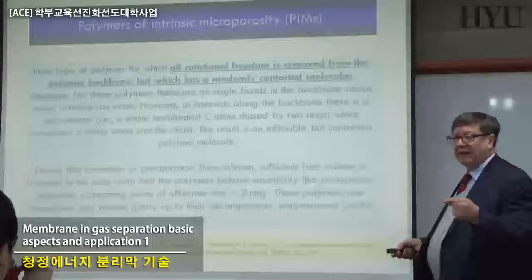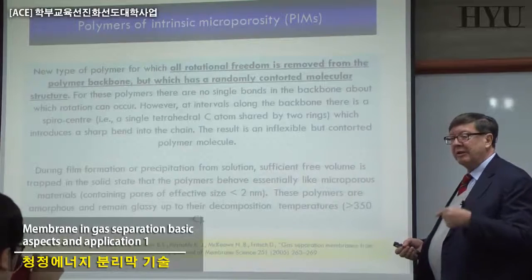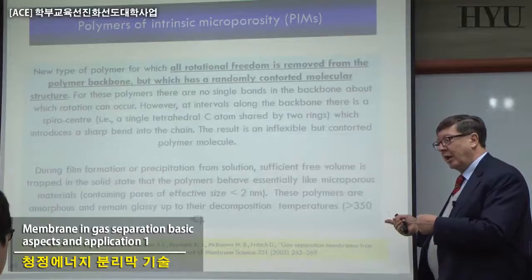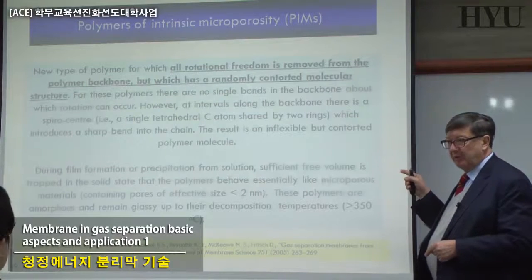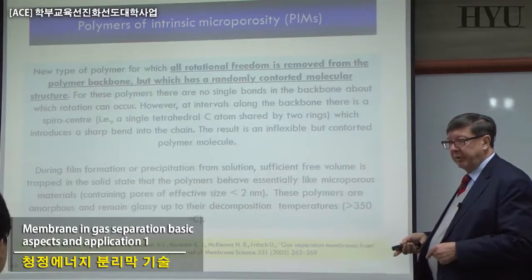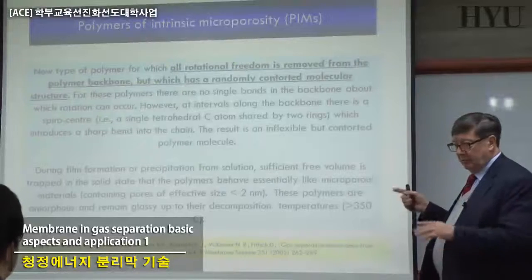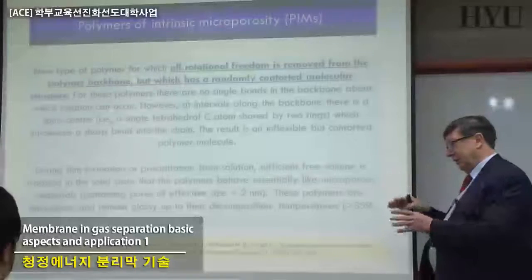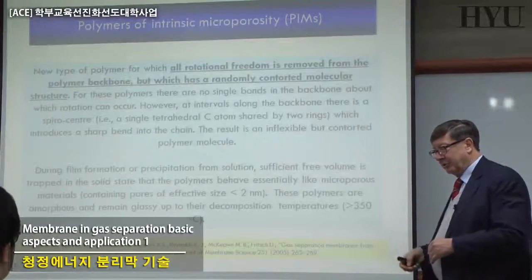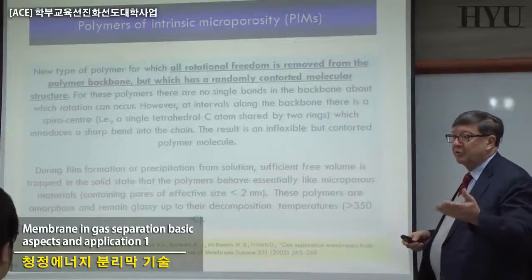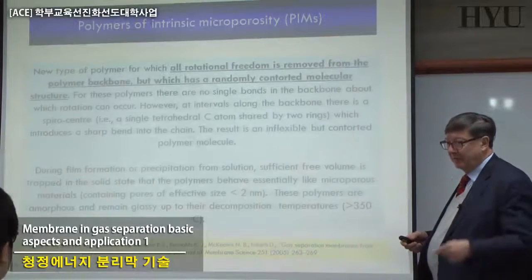We call it thermal annealing. And this thermal treatment changes in an irreversible way the selectivity and permeability of traditional RO membranes. Not the same problem, because cellulose acetate is not this kind of polymer, but post-treatment is always something that you have to try.